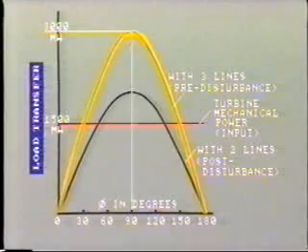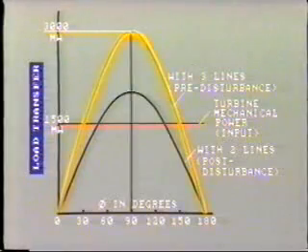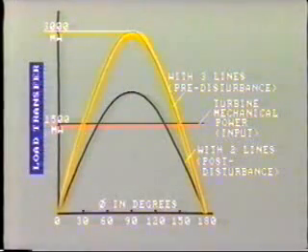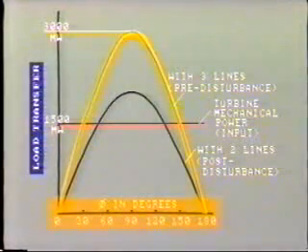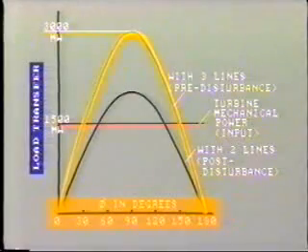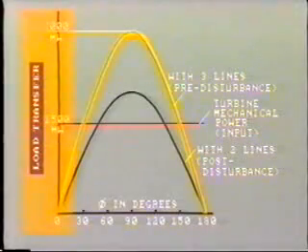At a power angle of 90 degrees, the capacity of the transmission circuit is about 3,000 megawatts. This curve does not show speed or frequency, although it is a sine wave. It indicates the phase angle difference between the 2 voltages at each end of the line and the corresponding quantity of power which is being transferred.